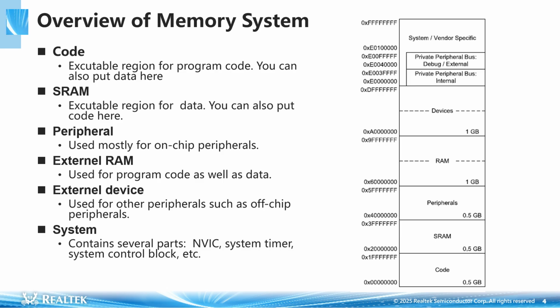The address bus of ARM Cortex-M series are 32-bit, providing an addressable space of 4 GB. All internal and external storage or peripheral units must be operated through their corresponding addresses. Different chips have varying types, quantities, and address spaces for peripherals. To facilitate more convenient management of different chip designs by the core, the ARM core provides a predefined memory map, as shown in the figure below.